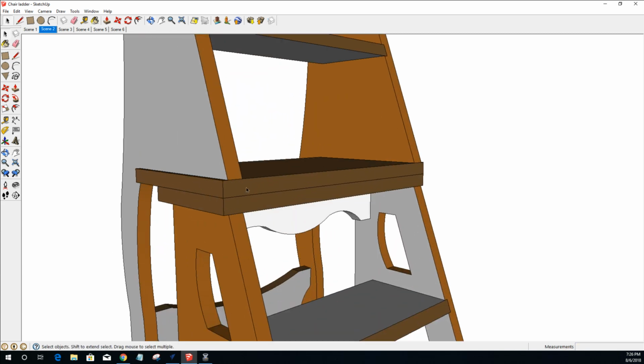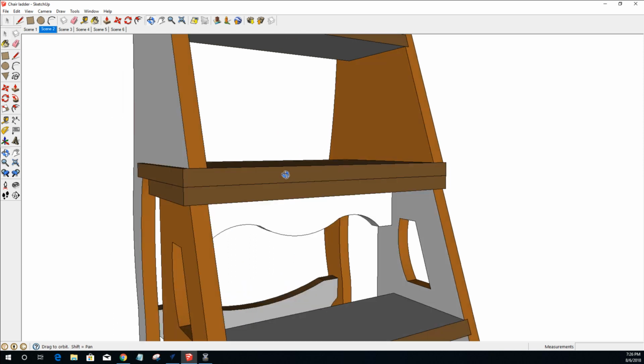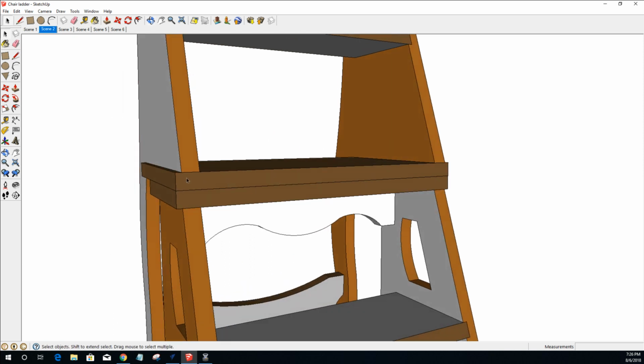When it's rotated, a lot of people on the design use a piano hinge here on these 2 parts for the hinge mechanism. I'm not a big fan of the piano hinge because the piano hinge itself, actually, when it's in chair mode, kind of sticks up above the seat of the chair. It makes it very uncomfortable to sit on.